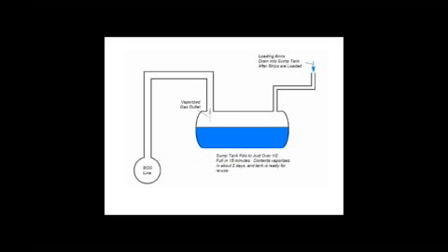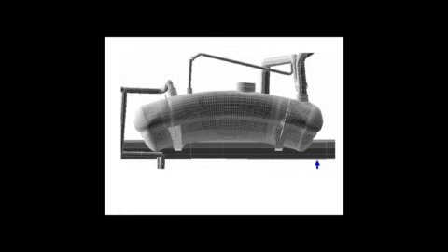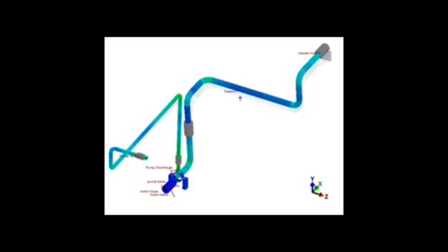All right, here's another model. This is an example where we've got a vessel. You say, well, why am I worried about a vessel with piping? Well, if we go to the next slide, what you see is piping can definitely move the vessel around. You can see that at the end of the system, we've got a branch connection coming off the vessel that's definitely bending this very, very large D over T vessel. The FEA technology in FEA Tools is not limited to D over T of 100. A lot of vessels have D over T's greater than 100.